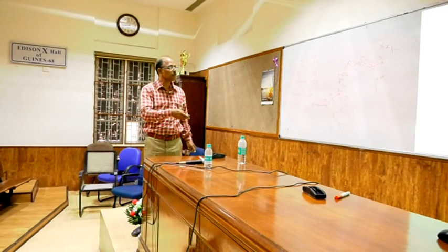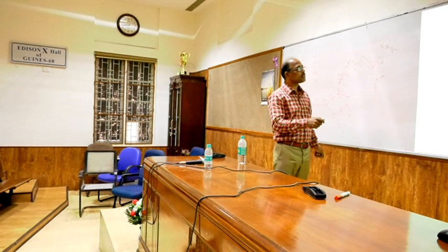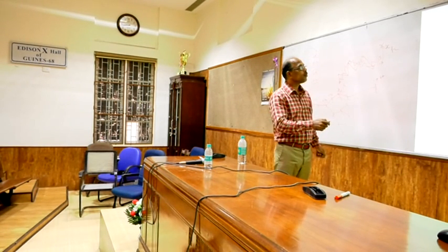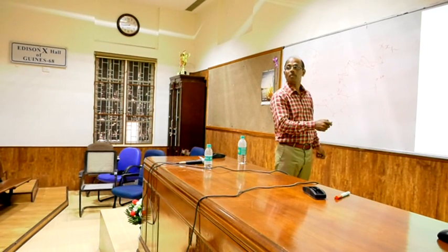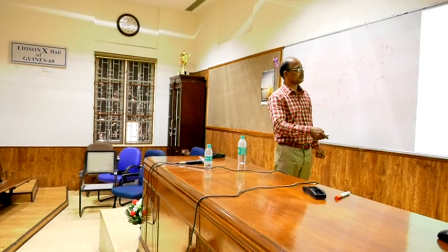So let us come to the previous diagram. This voltage drop is known, this voltage drop is known, this voltage drop is known. The voltage drop between the source node and this node is nothing but the voltage drop in this branch. The voltage drop between 0 and 2 is this voltage drop plus this voltage drop. The voltage drop between 0 and 3 is this voltage drop plus this voltage drop plus this voltage drop.